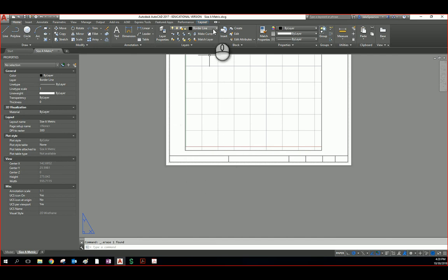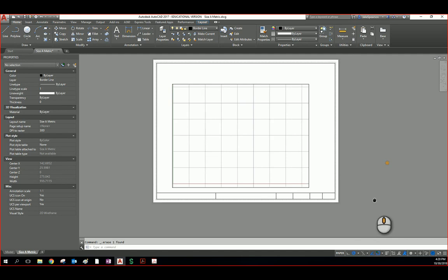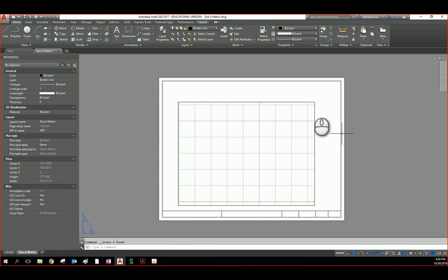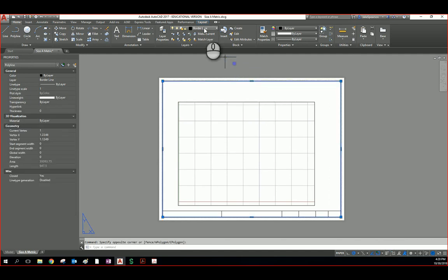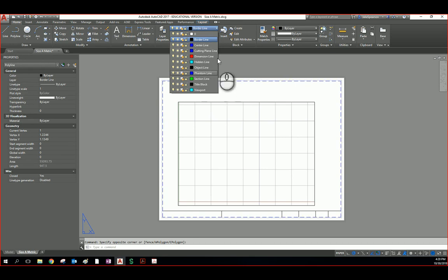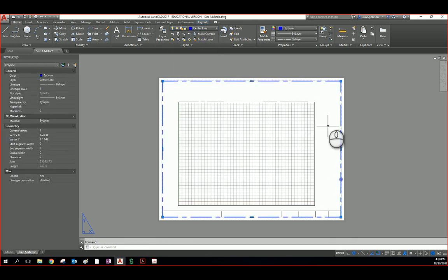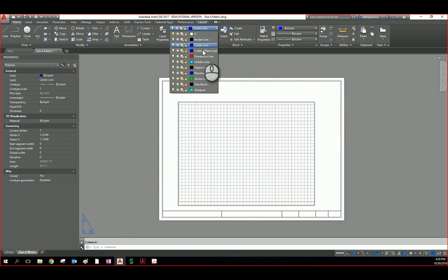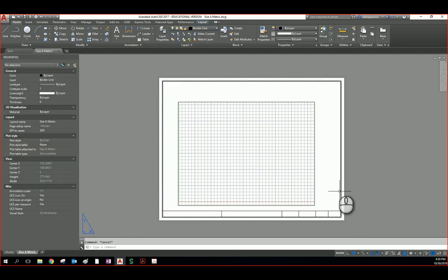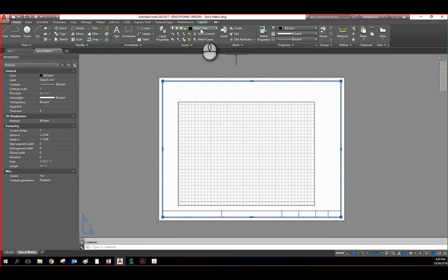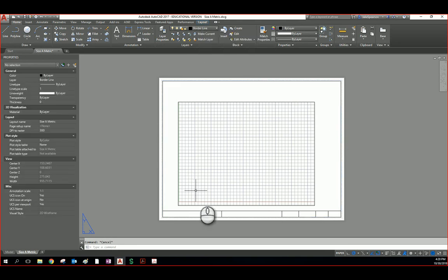And they're all border. A real quick way to identify whether it's border or it's something else is either you can select it and it'll light up and do something different. So like, here's an example. I mean, it looks like a center line, right? But if I make this, let's say, an object line, we can't really tell the difference. Okay, I can physically select one of them and it'll change up here. Okay, or I can do a little method that's called a line weight, showing the line weight, meaning the thickness and how fat it is.